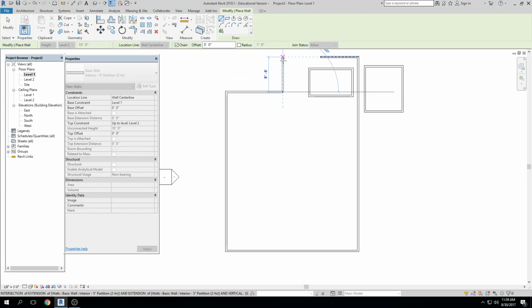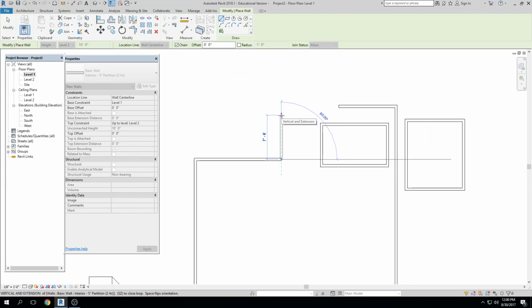Click. Do you notice that I'm getting a little bit of a hint of an object snap? An object snap in AutoCAD will allow you to draw lines orthogonal, right? So we have ortho, we have polar tracking, we have, well, just kind of iterations of that, I guess, that help us draw straight lines, polar tracking, polar, and then ortho, right? We also have things like midpoint, endpoint, nearest, perpendicular to help us get those lines exactly where we want them